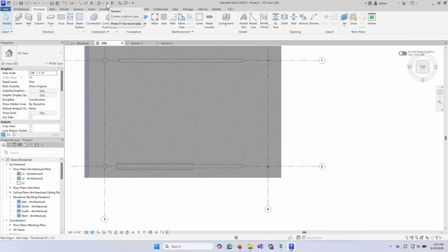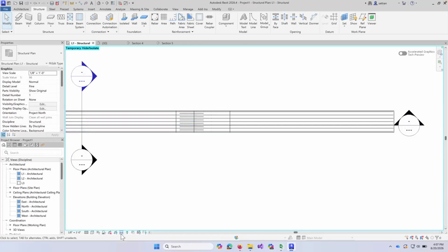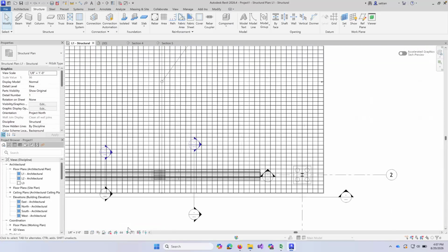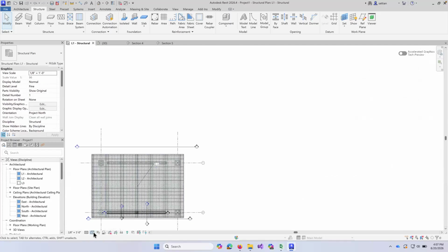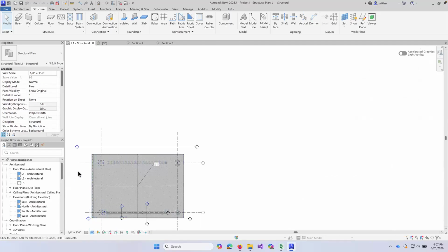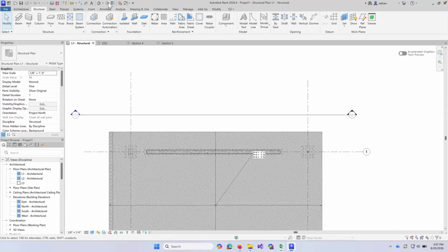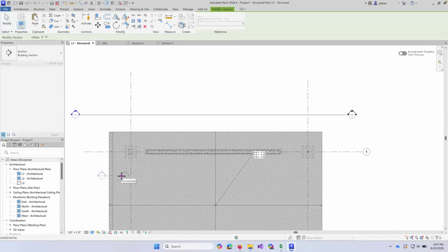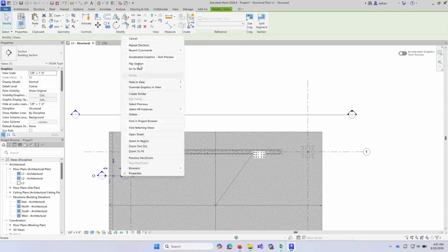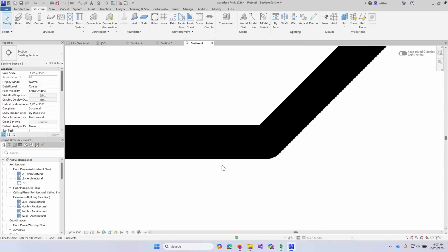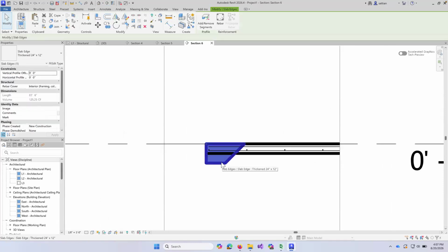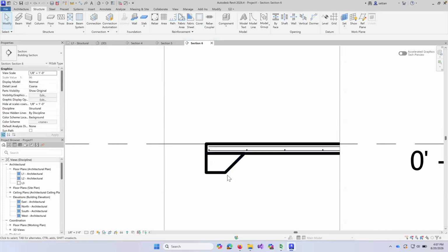What do you mean by that? Well, let's cut a section, look at it. Oh, can't do it in 3D view, sorry. So let's reset this view and go to wireframe to shaded. So now if I want to cut a section, and go to that view, you'll notice how this is the slab edge, but it goes in with the top of the slab. Well, a slab edge needs to go with the bottom of the slab, so I'm just going to drag it to the bottom. That's what a slab edge should look like.